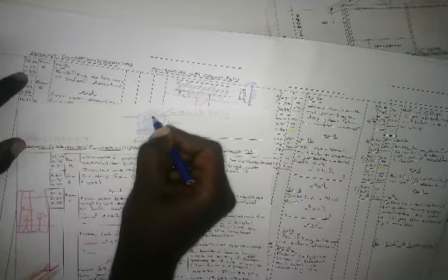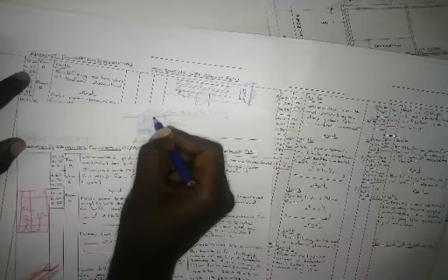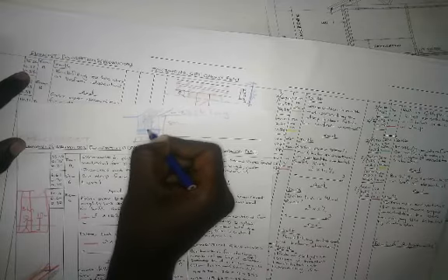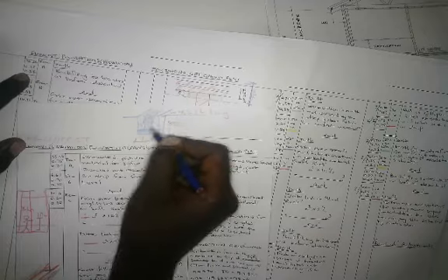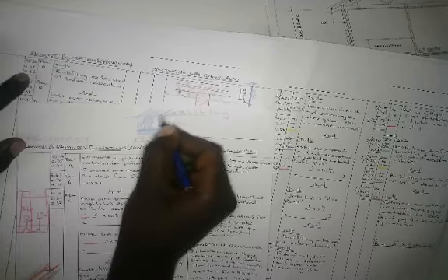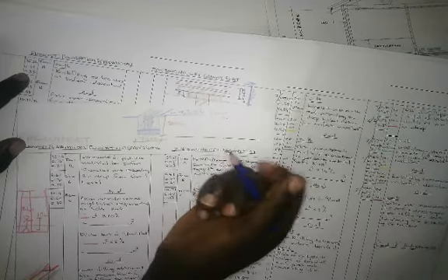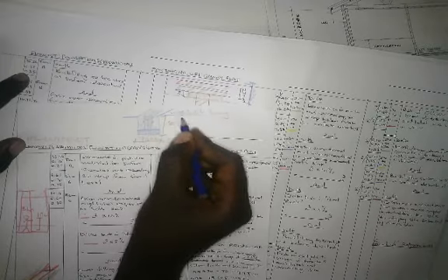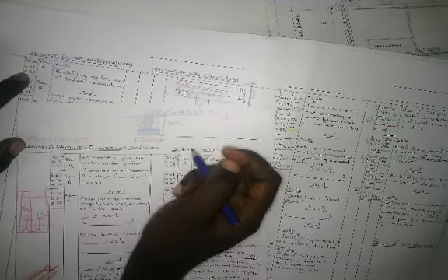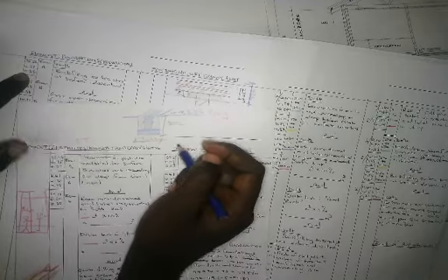So we're going to say 35.56, which is our centre line, divided by 0.27, which is the width of my 270 cavity wall, times 0.84, which is the height of my foundation brick wall, to ground level. Remember it must come to ground level.